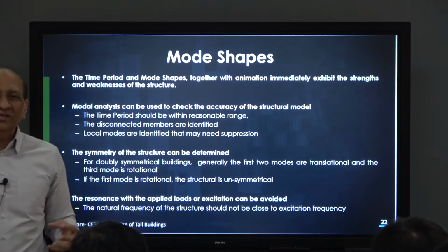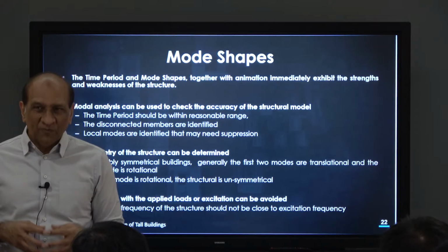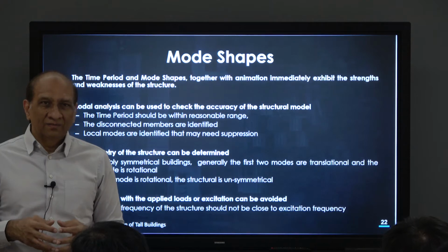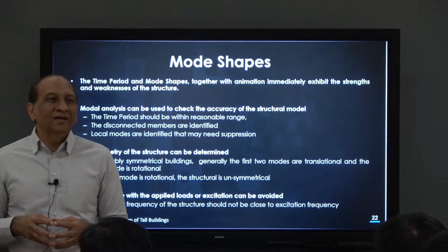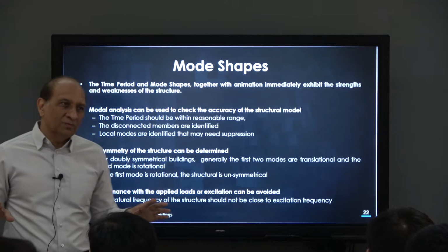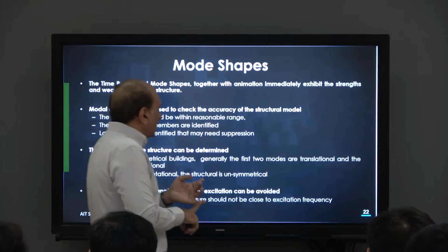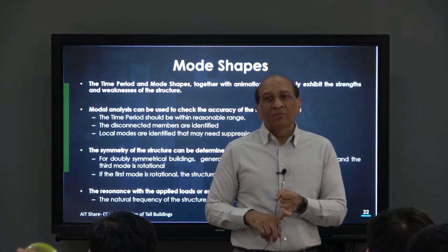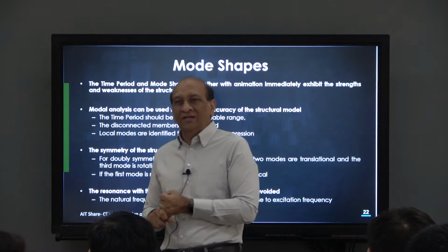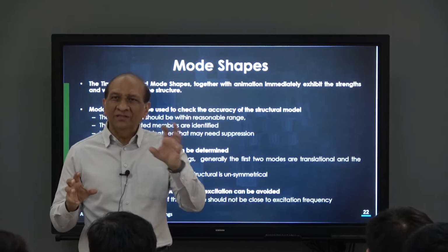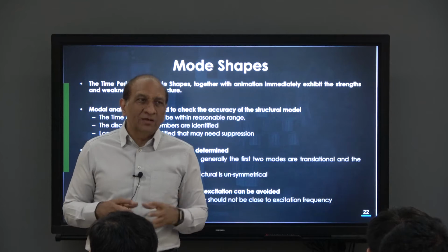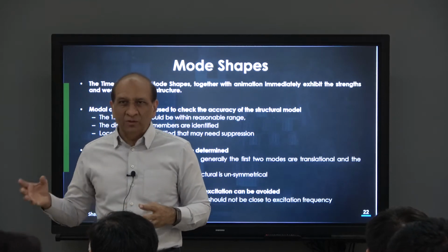There are many formulas to estimate the first natural periods. First primary natural periods are normally estimated by a number of formulas. The most simple formula is related to the number of stories. So people say number of stories divided by 10. That's not really something that you can lock in, but okay, it's a good number to start with. It depends on many things.